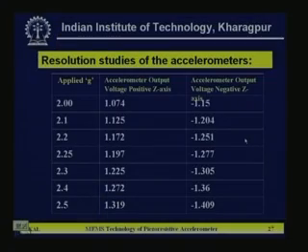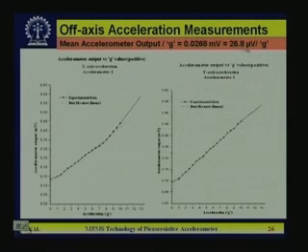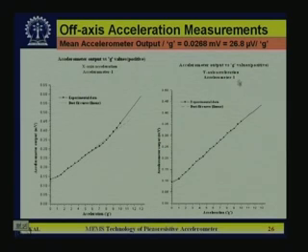But here you will get a value of nearly 26 microvolt per G. So it is 500 microvolt per G in the z direction and only 26 microvolt per G in the x and y directions. So off-axis sensitivity is less, but we have to agree that it is not as low as the design value, because of various reasons, such as fabrication tolerance, which is not exactly as estimated in our design. So off-axis sensitivity is not that high: it is 500 against 26, at least more than one order less.